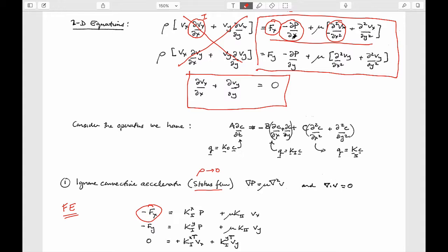And it operates in the x direction, so this x is here. And if we look at these terms which represent the viscous losses in the system, they're both due to flows in the x direction, but they're due to a gradient in both x and in y. And so this is the term that represents that, but they only actually operate on velocities in the x direction, this one here. Right? So take that on trust.